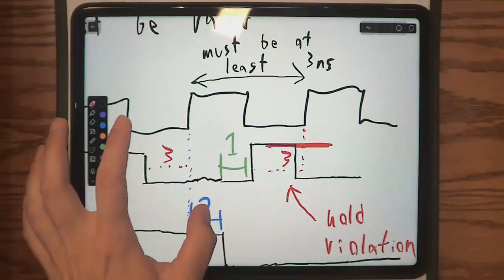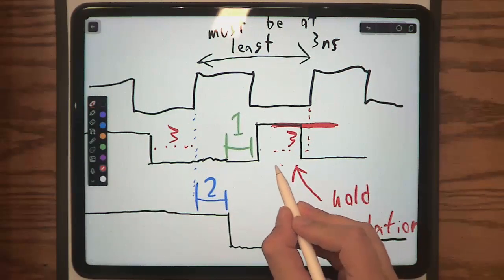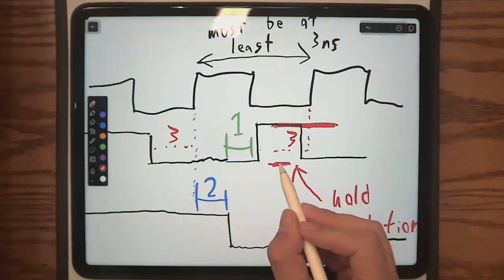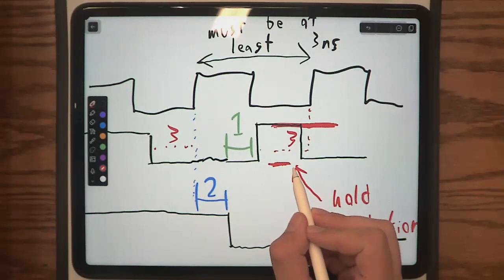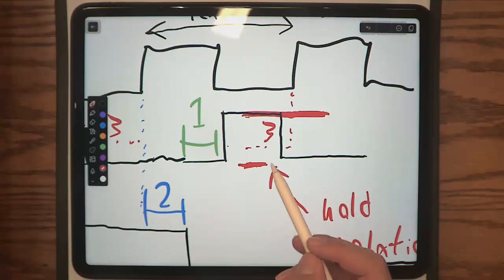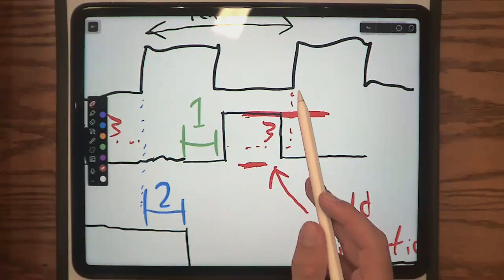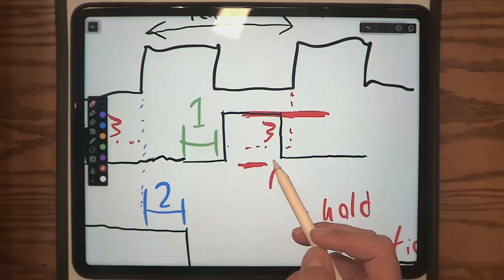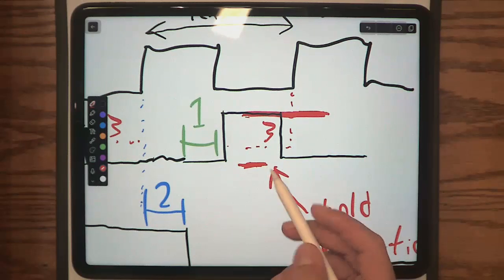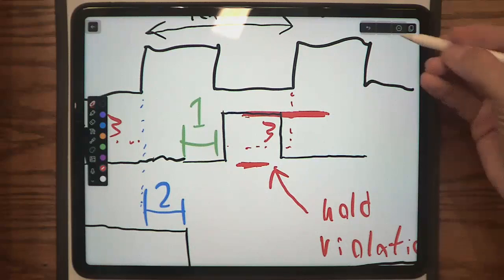But you can also have flip-flops that have very short timing apertures. You can have them sampling maybe in this region right here. So they are fine with you changing their value right before the positive edge. You see that? If you change the value right before, it's still okay, because this is the only window that it actually samples in.